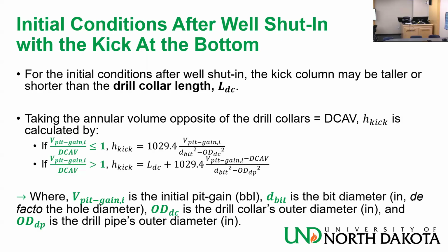Sometimes people run the BHA downhole, something happens and they need to see the design of the BHA, and you ask to see it, and they don't have it, or they are not certain. Because when you have to go fish something, you want to say, okay, this is where we got stuck, this is where we cut.